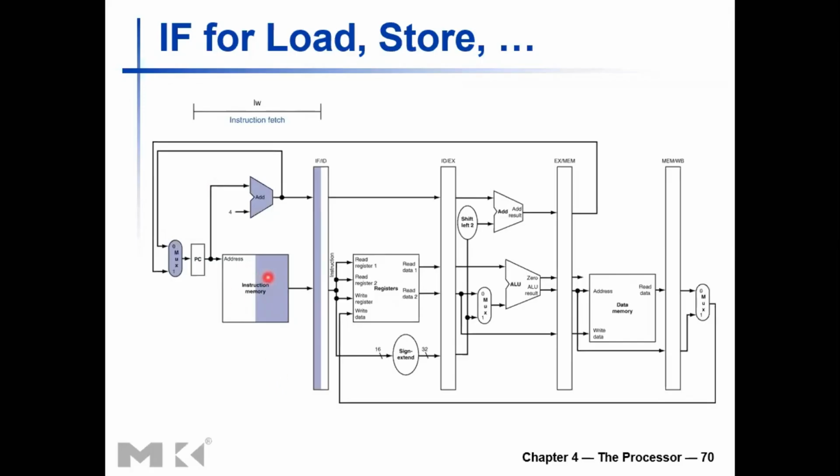So instruction memory reading, we don't have a control signal, right? Reading happens asynchronously, and this adder doesn't need a control signal. Program counter doesn't need a control signal. So those are the pieces of hardware used here. The multiplexer is actually used in the memory access stage. So the signal had already propagated through the multiplexer into the program counter by the start of this current clock cycle, right?